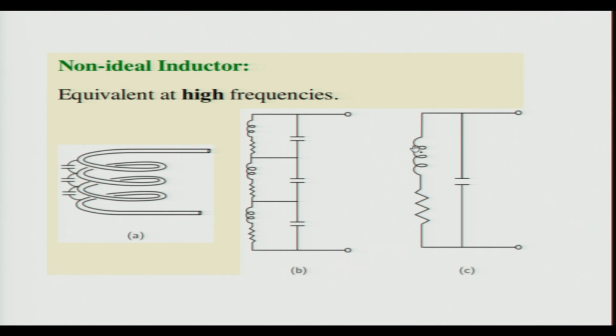That happens at low frequencies because the current through the capacitor at low frequencies is small. Why is it small? Because when there are smaller rates of change, the amount of current is going to be less, since the rate of change of voltage into the capacitance is what gives the current. At low frequencies this effect is very small, because this capacitance is quite small.